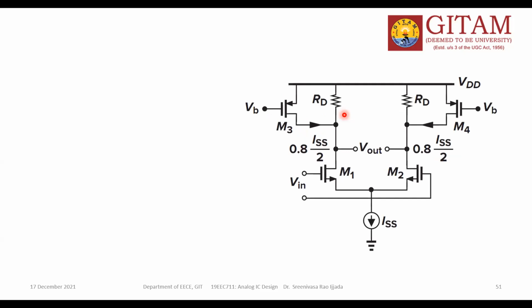Yeah. So now again the diode connected loads in the circuit are replaced with RD. So in the previous case, because there are two diode connected transistors, at any cost you will get the output less than one threshold voltage of the device. At any time each diode should be on, so VTH is the minimum required, so that the drop across the diode connected load is always VTH, the minimum voltage drop.